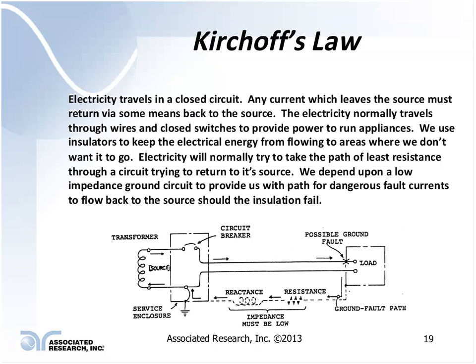The battery buzzer combination is a little dangerous. You can have one conductor of your line cord and pass a continuity test, but there's no way it's going to be able to handle any fault current. And how important is this ground circuit?